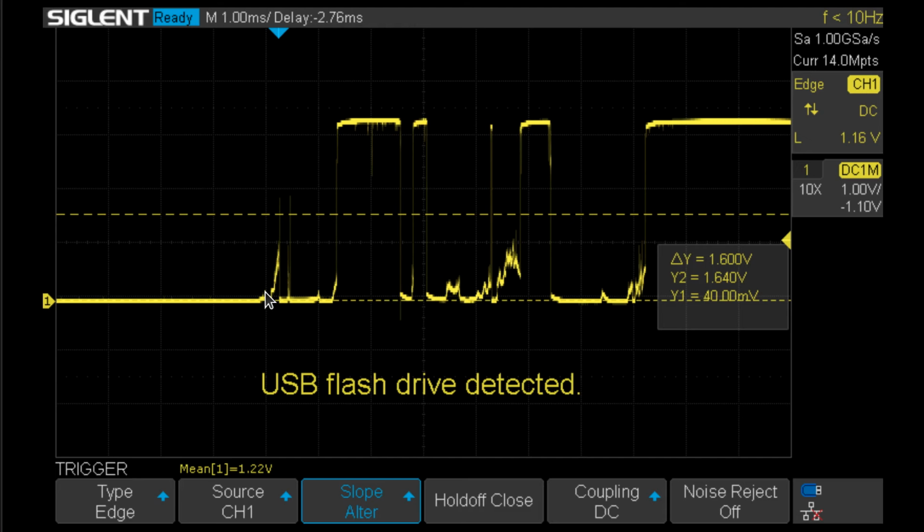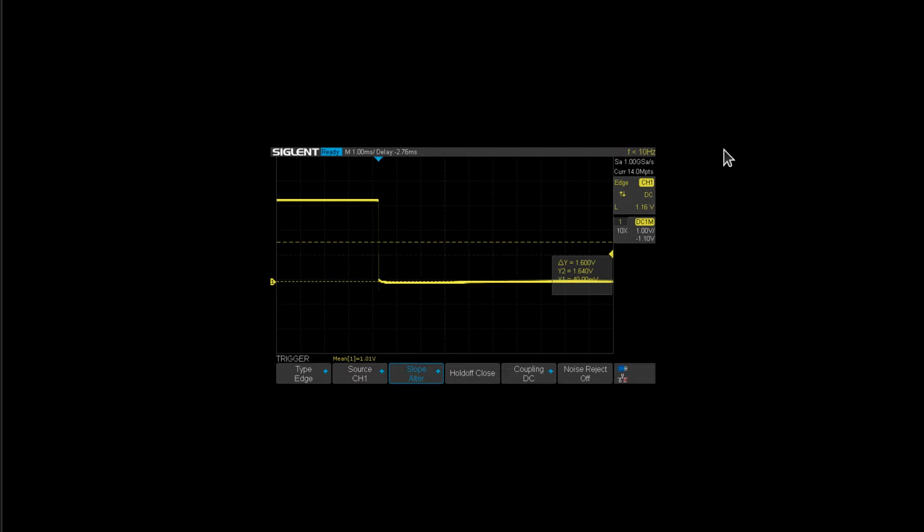On my board, when I press it, it goes low, and when I release it, a pull-up resistor pulls it back up high. As I release my button, it's literally bouncing. The contacts are bouncing in here, and so if I set it to 10 milliseconds, this would be clean. It would ignore all this, and it's not till here plus 10 milliseconds later that it'll say it saw it go high and stay high and stable for 10 milliseconds, and then it will change the output from the debounce circuit. That's not too bad.